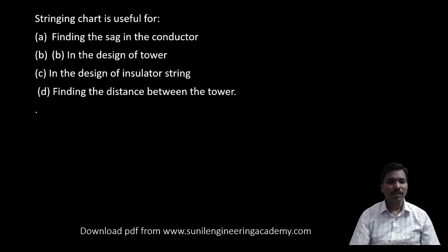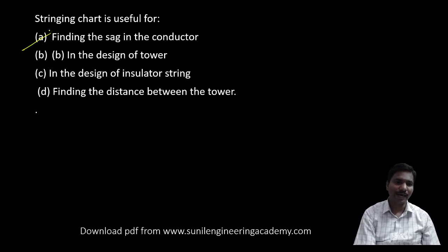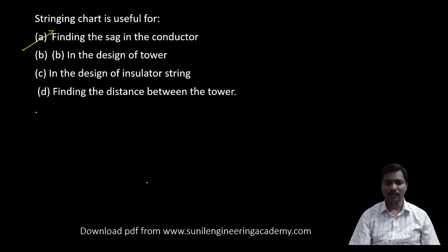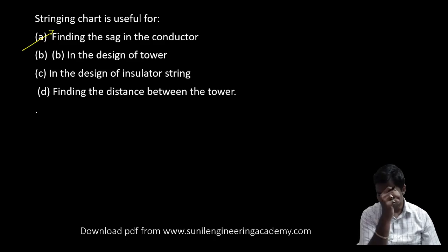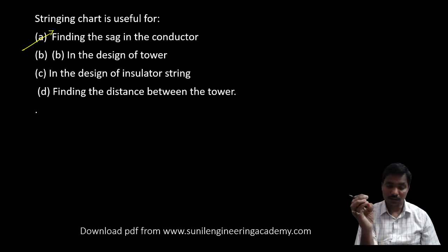Okay. Stringing chart is useful for dash. It is useful for finding the sag in the conductor. Not stringing, that is not string voltages or string efficiency. It's not for designing of insulator string. It is used for finding the sag.